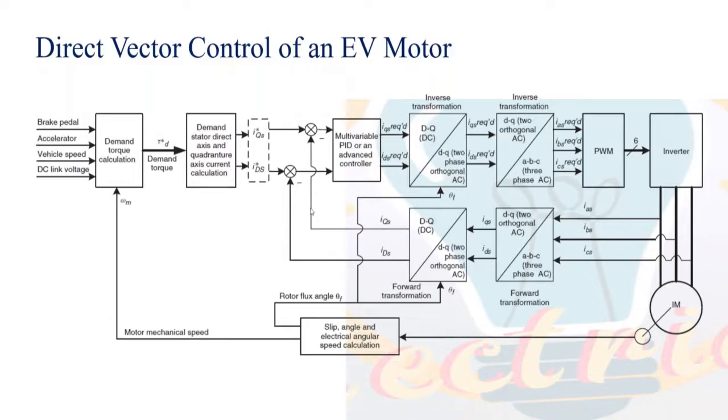Now you know the PI controller, proportional integral. Basically, we use it in control systems. This PI controller needs the input. This is the input signal, and this is the reference input. The reference is coming from the driver. The driver is pressing some accelerator, right? Based on that, the controller determines what current it is expecting, and that is compared with the current coming from the motor.